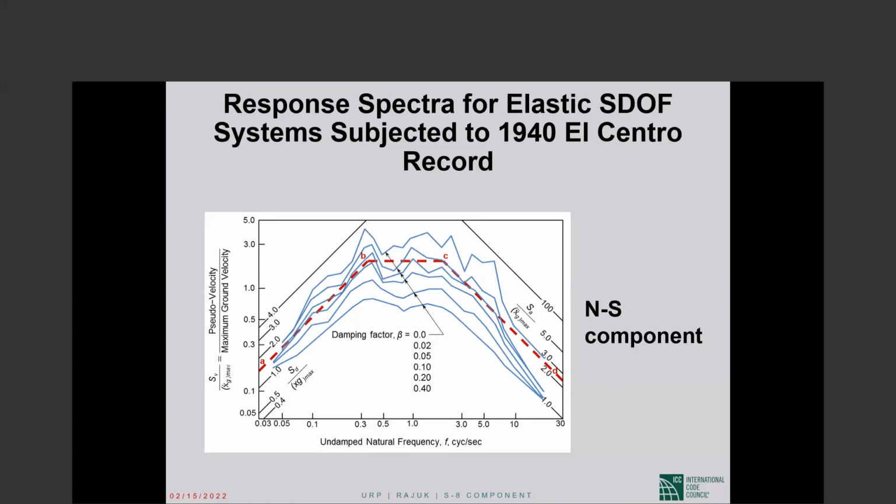Okay. Then what Professor Newmark has done is to indicate that the 5% damped spectrum, this is 0, this is 2, this one is 5%, the third one from the top, that spectrum, he indicates, can be approximated by the 3 red lines. Okay, so the 3-part red line is an approximation of the 5% damped spectrum.